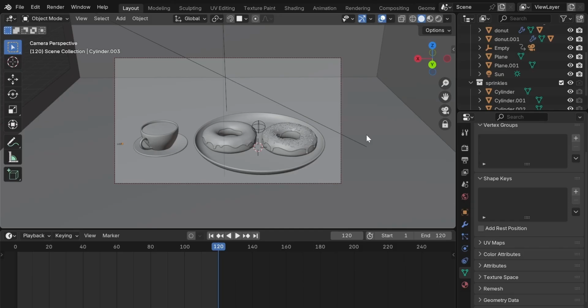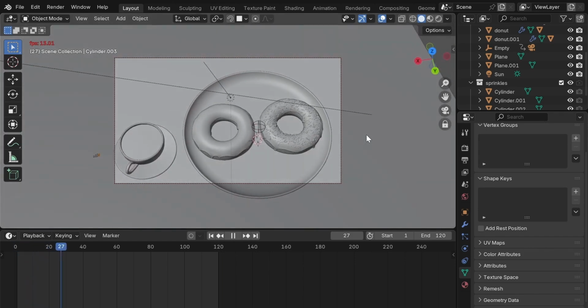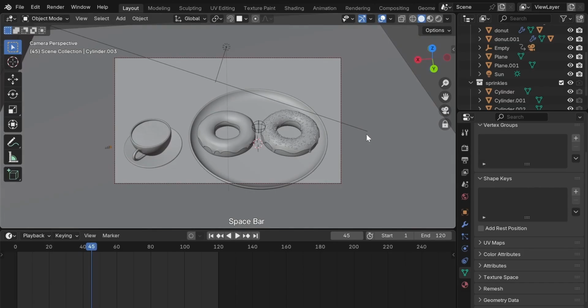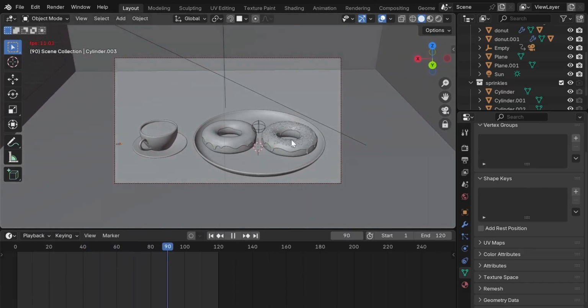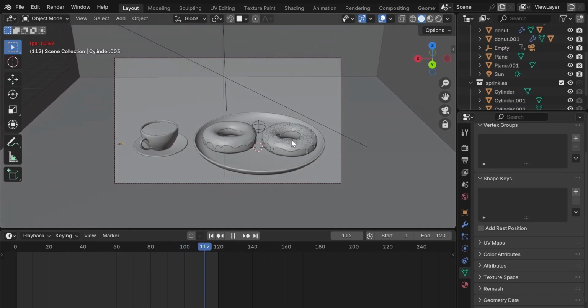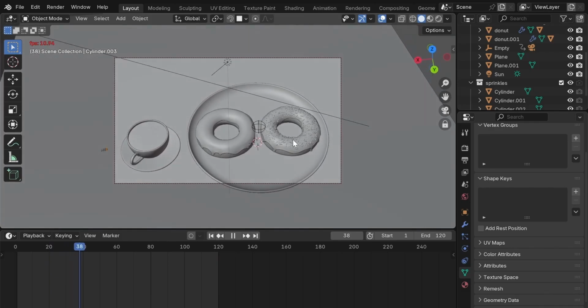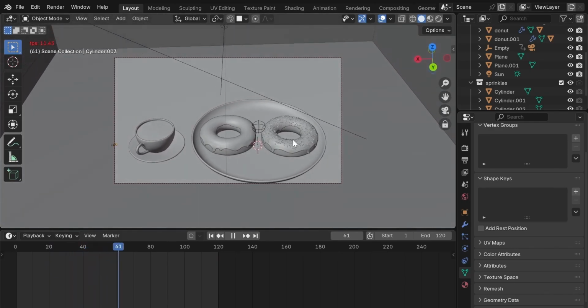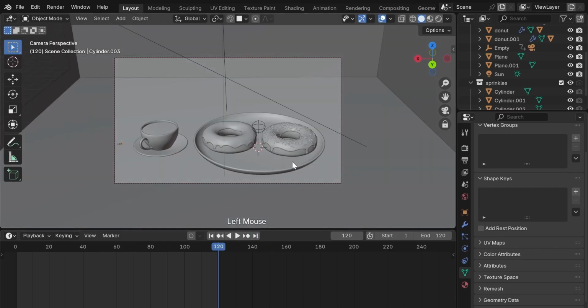When rendering a single image, you won't notice any issue. But during animation, Blender recalculates the random value for every frame. That means the sprinkles would change rotation and scale continuously from frame to frame, which obviously isn't realistic. In the real world, sprinkles don't shift or rotate as the camera moves. They stay fixed in place. So to fix this, we need to apply the Geometry Nodes modifier.